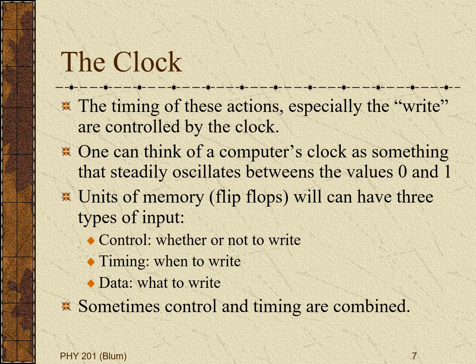One of our examples of a sequential logic circuit was a counter. So now let's think about what happens with a counter. You give it an input that tells it to increment, and it takes its state, say 34, and makes it 35. But if the state is still saying increment, then how do we know that the 35 is not going to become a 36 and a 37 and a 38? Well, when we have sequential logic, we also have to introduce the concept of the clock, that we will respond to our input at a given time.